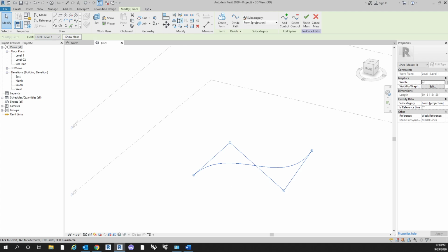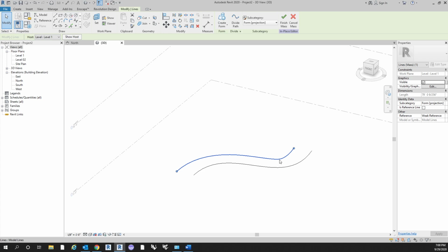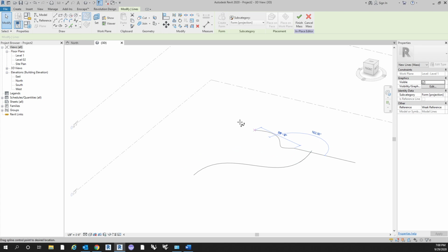If we offset or mirrored this curve, and make it larger so you can see where. So if we offset that curve, it does offset and it offsets correctly. Problem is when you click that offset curve, it loses all of the control points that are associated with it, and all you can do is change the location of the endpoints and either scale it up or down.